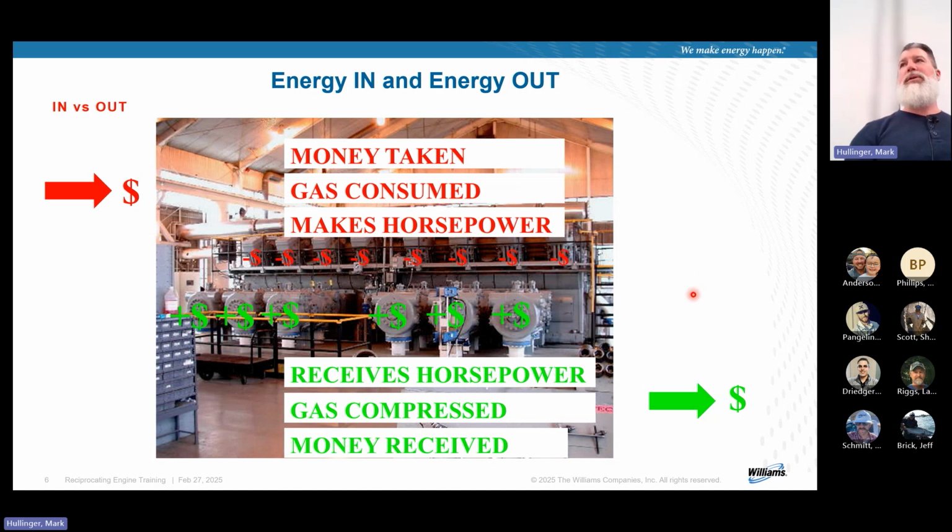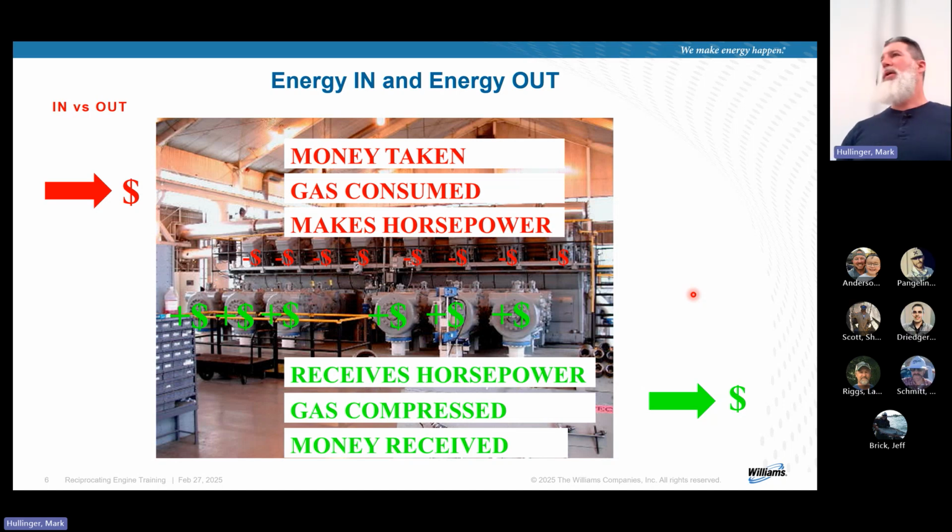Those factors, by the way, are in the PLC and part of the mapping, which you don't have to worry about. But there are ways we can measure that on our engine analyzer, which is kind of cool. And on the compressor side, there are also some friction losses. What we've measured is usually about 95%, so 5% is lost from there.